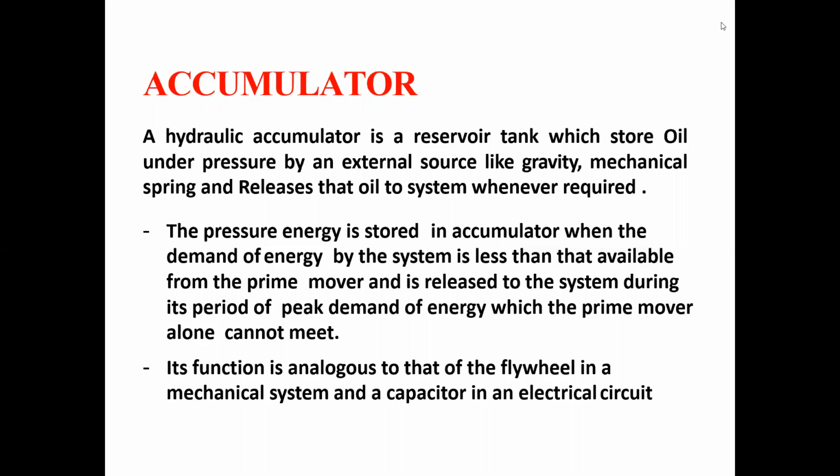So what is an accumulator? It is a component which stores high pressure oil. The pressure energy is stored in the accumulator when the demand for energy by the system is less than that available from the prime mover, and it is released to the system during its period of peak demand of energy which the prime mover alone cannot meet. Here prime mover means pump.